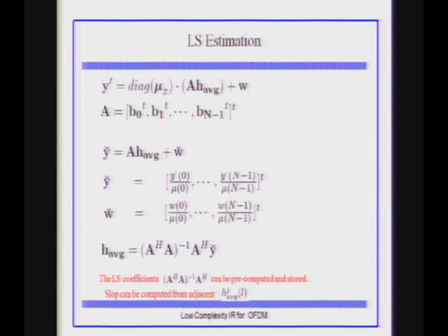In our simulations, we have around 10 or 20 OFDM symbols that constitute a packet, and that goes into the BCJR. So with 20 OFDM symbols, you compute the H averages for all of them, and you compute the slope for each of them. For the last OFDM symbol, we just approximate the current one to the next one, and we refine it when the new block comes.